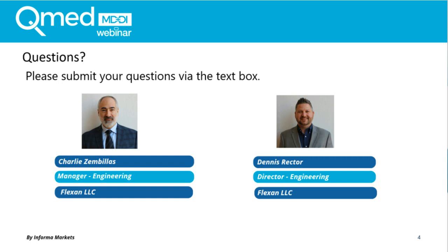What our silicone vendors do as mitigation for fiber and particulate and contaminants is they use what's called a screen mesh, usually a 200 by 200 or 300 by 300, so it filters out the A and B components of the elastomers prior to final packaging. And likewise, in our process, we use a screen mesh filter pack within our extruder to also further filter out fiber and particulate. All right, thank you, Dennis.